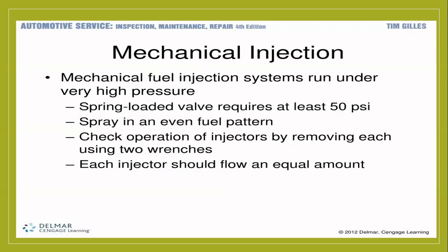Mechanical fuel injection system works under very high pressure. This is very important. A spring-loaded valve is required, at least 50 psi. Normally, our carburetor works at 5 psi, 5 to 10. Here you see 50 psi, high pressure lines. Spray in an even fuel pattern. So your diesel spray pattern should be even. Even means equal distribution, right?